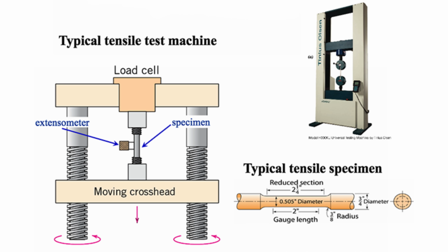D3039, in which one end of a rod or wire specimen is clamped in a loading frame, and the other subjected to a controlled displacement, delta. A transducer connected in series with the specimen provides an electronic reading of the load P corresponding to the displacement. Alternatively, modern servo-controlled testing machines permit using load rather than displacement as the controlled variable, in which case the displacement delta would be monitored as a function of load.